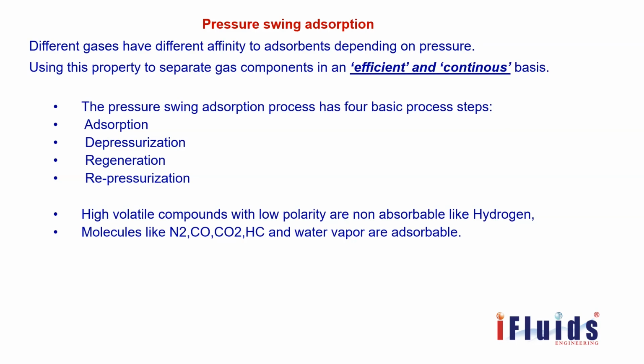Once the adsorption in a single vessel is over, it has collected all the impurities, including any hydrocarbon, and attains the saturation limit. With further feedstock it will not adsorb any impurity, so the impurity will escape along with the product hydrogen. So this we have to regenerate.